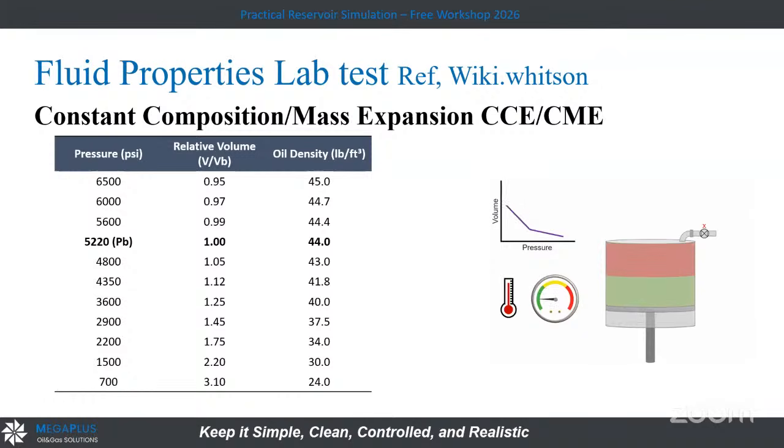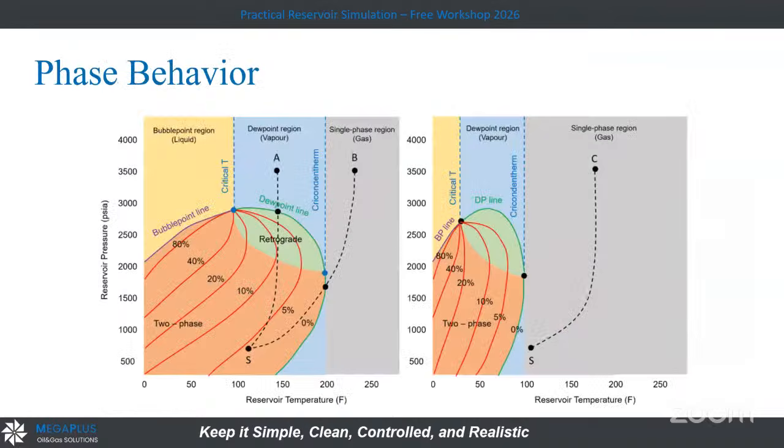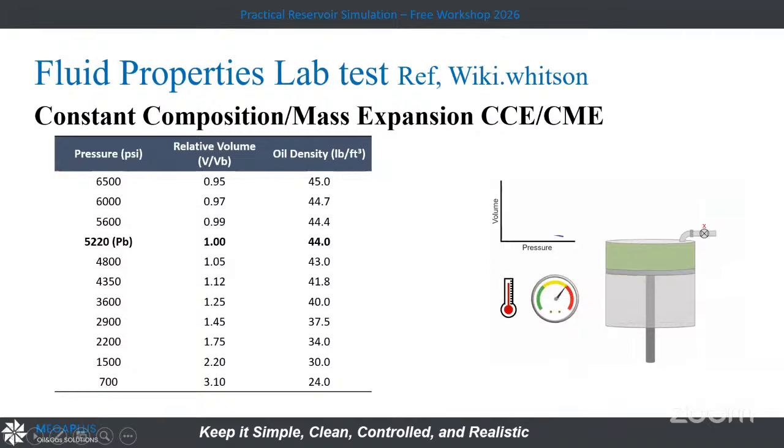At which pressure do we have the first bubble? So exactly what I'm doing is that I have the fluid here, and I start to decrease the pressure until the first bubble comes out, and then the gas will increase until we reach 40% liquid, and the gas is the rest. So this is the experiment that we have done.